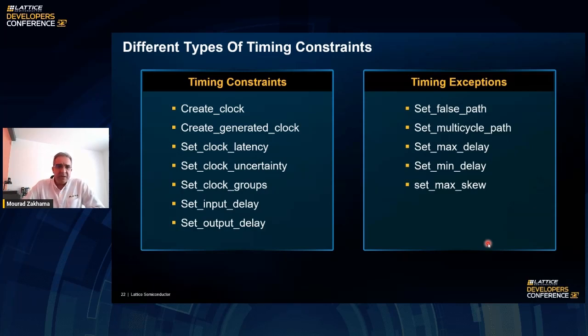And I'm not talking about the situation of a PLL. A PLL will automatically be identified by the tool, and the relationship between the input clock and the output clock will be automatically identified. But I'm talking more about, for instance, clocks that are generated by a clock enable situation, where you may be enabling the clock 1/4 of the time, for instance.